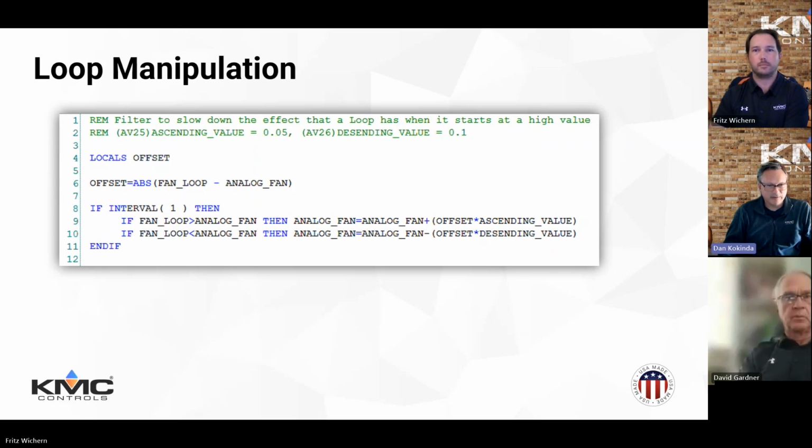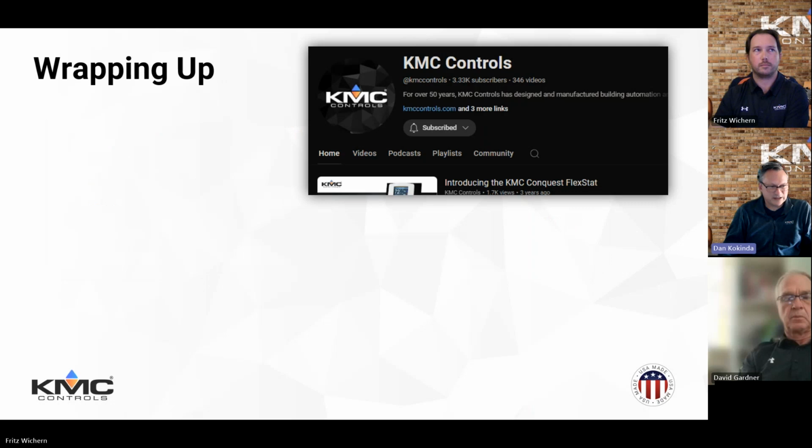But at the same time, you've got overhead, and you don't want to run wild if you're doing point passing. It's just the best practice to pull your data no faster than you really need to. If it's a space temperature, you don't need to know it every 5 seconds. Get it every minute or every 2 minutes or something like that, and just evaluate all your data.